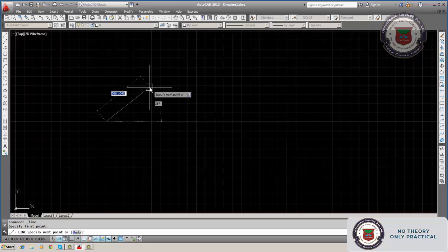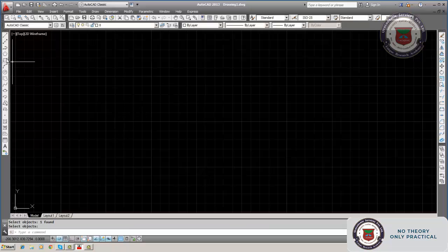Suppose I want to draw something somewhere here, 208, you have to enter the value here. See, 208.6, and here 30, 45, enter values and draw. So we have to enter the values in snap mode. This is called snap mode because the movement will be only in multiples like this. By clicking, you cannot draw fractions. You can draw lines only at the junction of the grids.